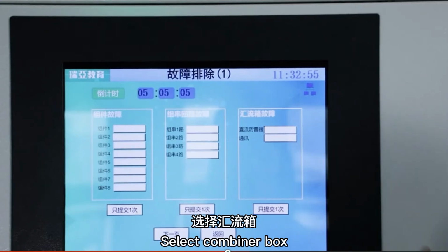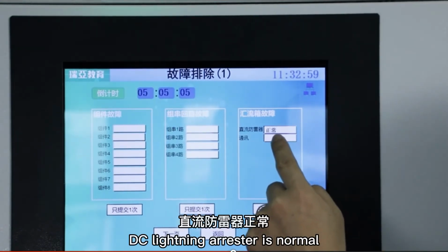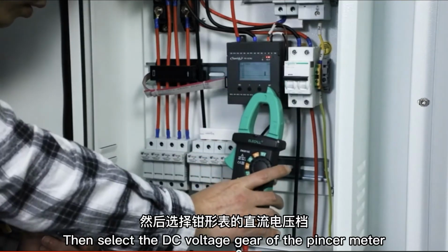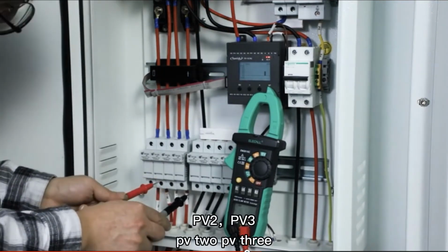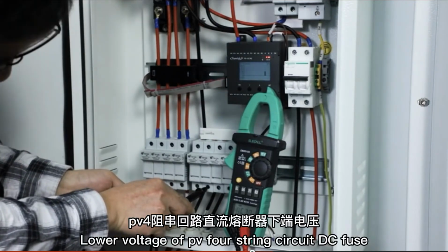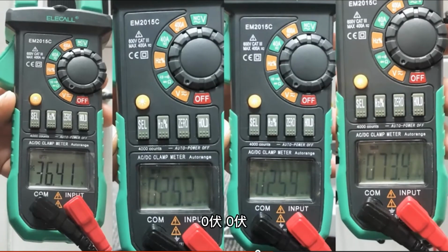Select Combiner box. Select a fault cause in sequence. DC lightning arrestor is normal. The communication line is normal and click Submit. Then select the DC voltage gear of the clamp meter. Measure PV1 to PV3 in the combiner box in sequence, and the lower voltage of the PV4 string circuit DC fuse. The displayed voltage is 36 volts, 0 volts, 0 volts, 73 volts.